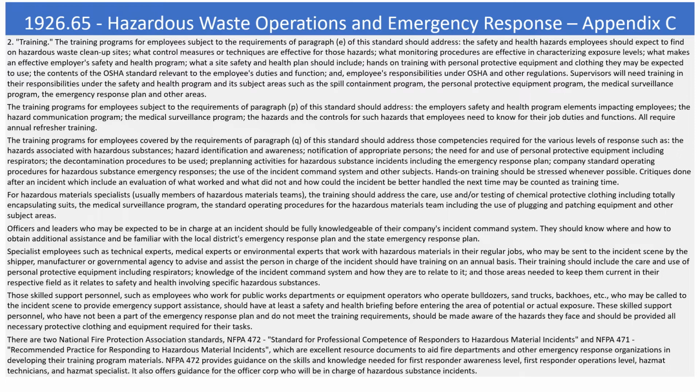Those skilled support personnel, such as employees who work for public works departments, or equipment operators who operate bulldozers, sand trucks, backhoes, etc., who may be called to the incident scene to provide emergency support assistance, should have at least a safety and health briefing before entering the area of potential or actual exposure. These skilled support personnel, who have not been a part of the emergency response plan and do not meet the training requirements, should be made aware of the hazards they face and should be provided all necessary protective clothing and equipment required for their tasks.